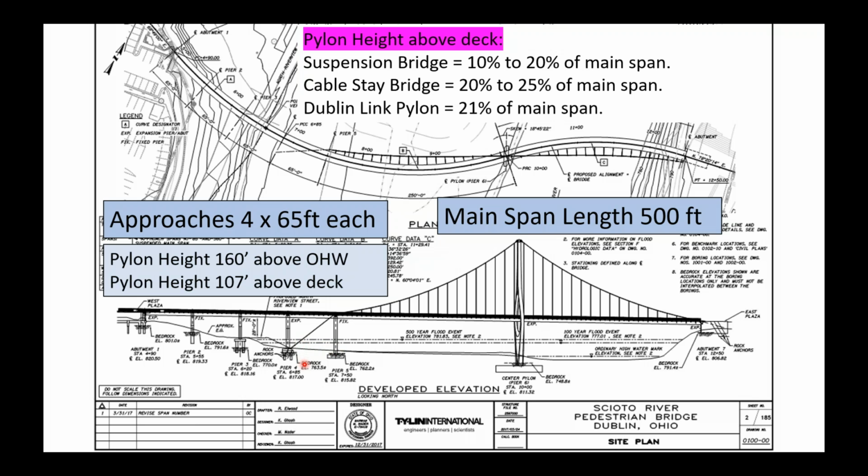So what we ended up doing was putting in a steel pipe protection on that cable, and so the bottom portion, all the way from the foundation up to above the 500-year flood level, is protected by a permanent steel pipe that the cable runs through, and that pipe doesn't prevent the debris from collecting there, but it protects the cable from being severed by any kind of debris that comes across there.